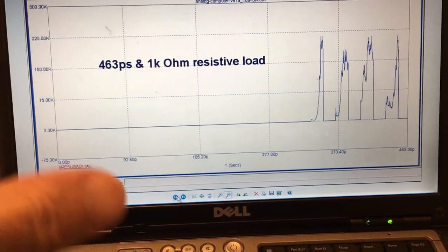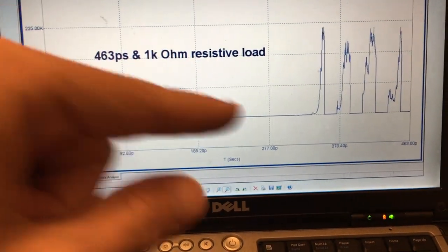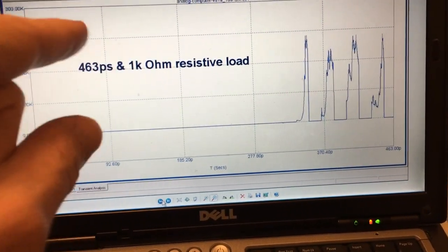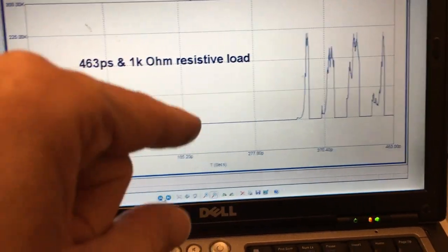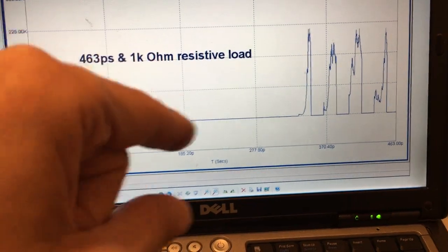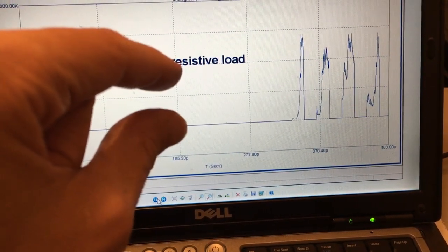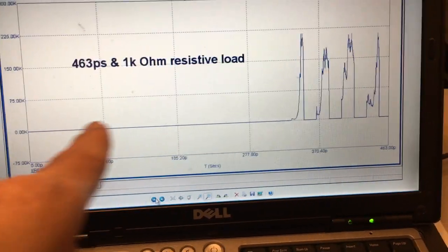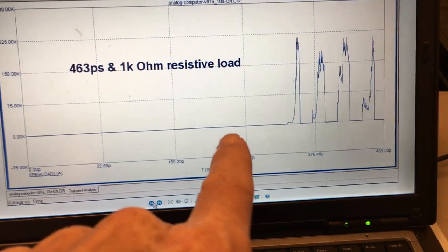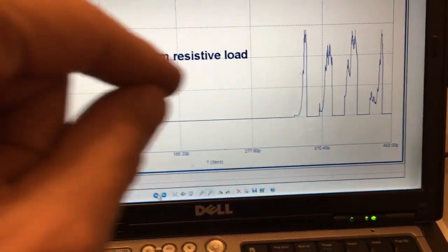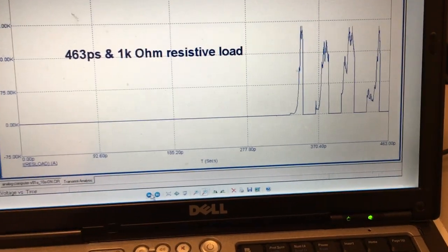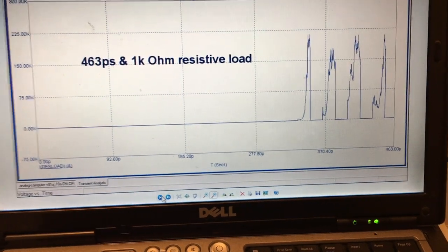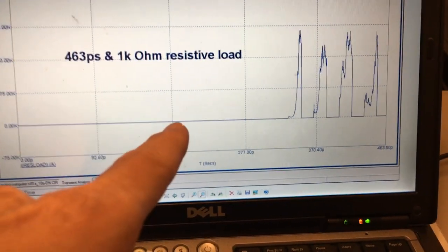And as you do so, if it converges, what happens is your output keeps changing. First it's too high, and then it's too low, and then it's too high, but the high is lower than it was the last high, and then it's too low, and the low is not as low as the last one. So it keeps moving in to midline, and you can do it infinitely long. It depends how many place values to the right of the decimal point you want accuracy, and that's convergence. But divergence, the highs become higher and the lows become lower, and the thing just wants to go to infinite gain, which is very interesting because that's what these circuits are trying to do anyway.